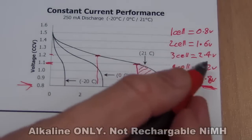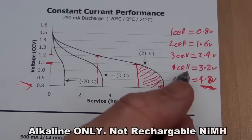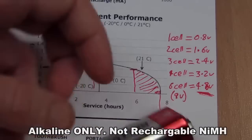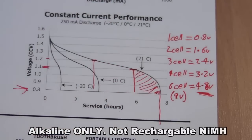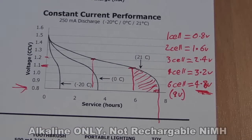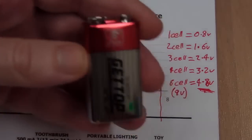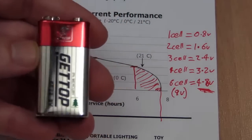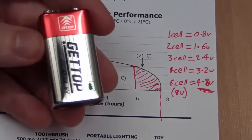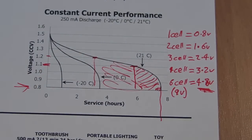For a 2-cell design, nominally 3 volts, 1.6 volts is what you want it to work down to. 3-cell and 4-cell, a nominal 6-volt system, 3.2 volts. And for a 6-cell system, or your standard 9-volt battery like this, ideally your product should work down to 4.8 volts. This is why in my product reviews you will see that I actually measure the cutout voltage of the battery. If a multimeter is working from this 9-volt battery and its cutout voltage is 6.5 or 7 volts, as some of them are, or even higher, then they're just wasting a ton of capacity in the battery. It's crazy. Don't do it.